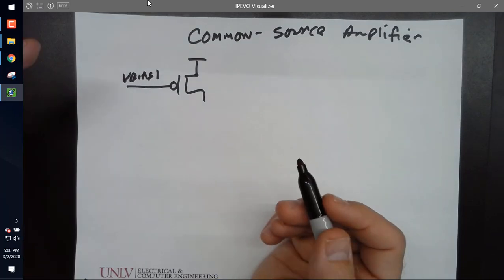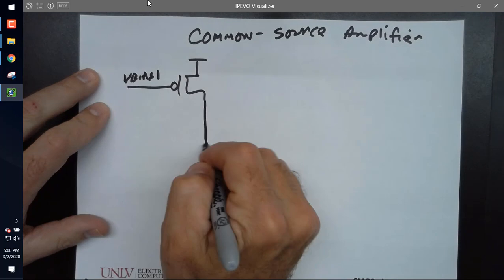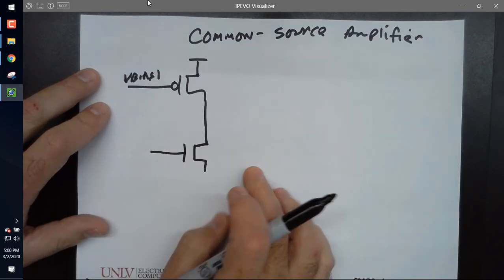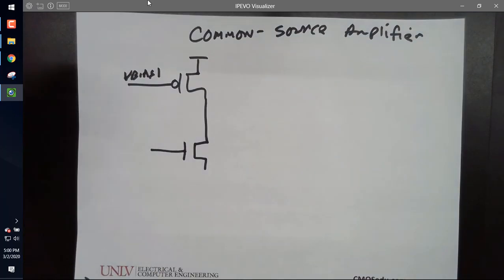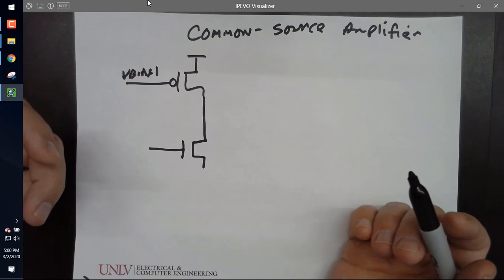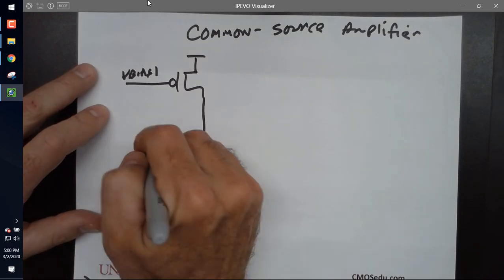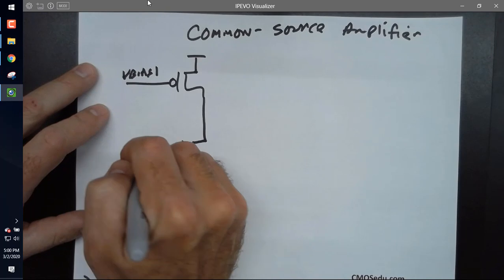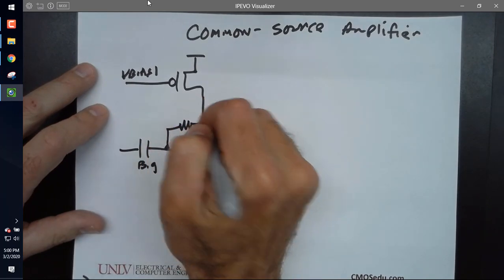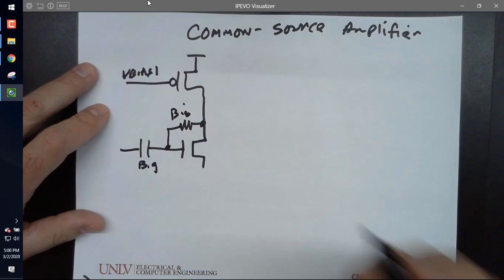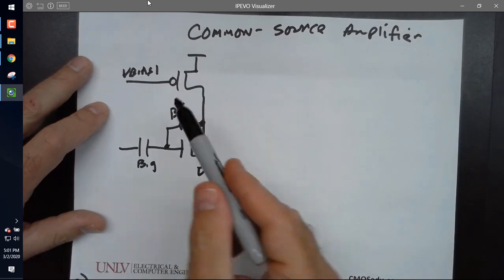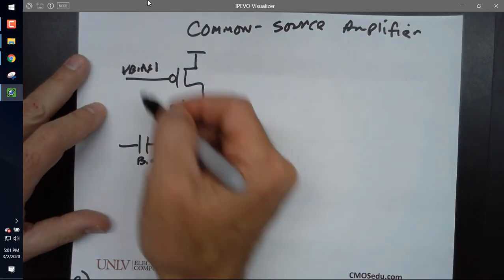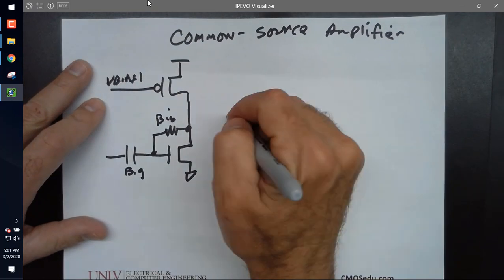Am I blowing anybody away there? And then I come down here. Now, there's no way I can make two current sources have precisely the same current, so when I put them in series, I have to be careful. Just like I don't put voltage sources in parallel because I can never get one to be precisely the same as the other. The one will end up charging the other. So here's the way I'm going to fake it. I'm going to put a big capacitor here that acts like a short, and a big resistor here that will not load the amplifier. And for DC, let me ask you, what do I think of this part of the circuit as in my mind? This part.